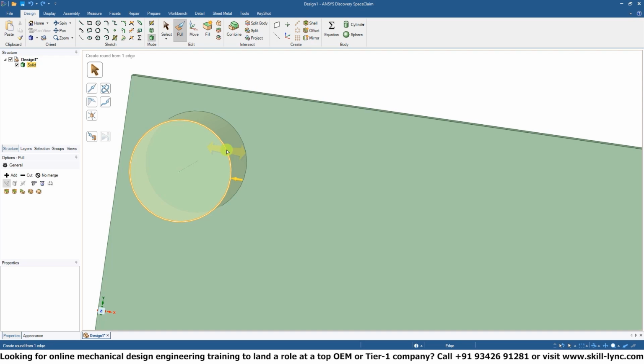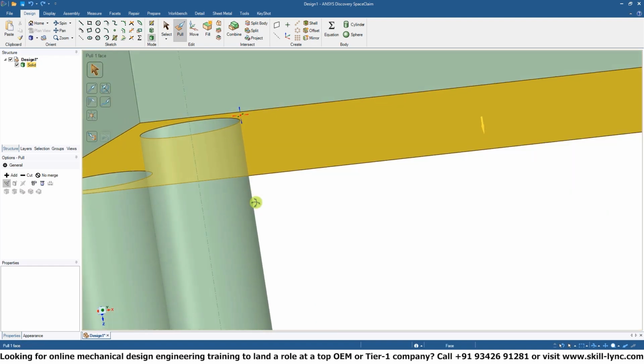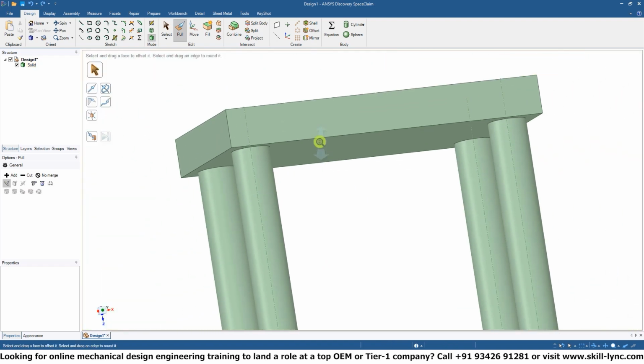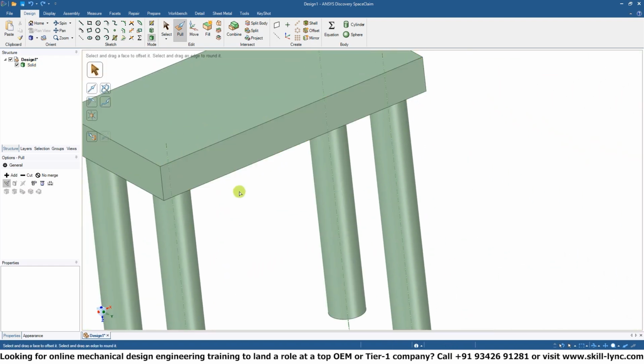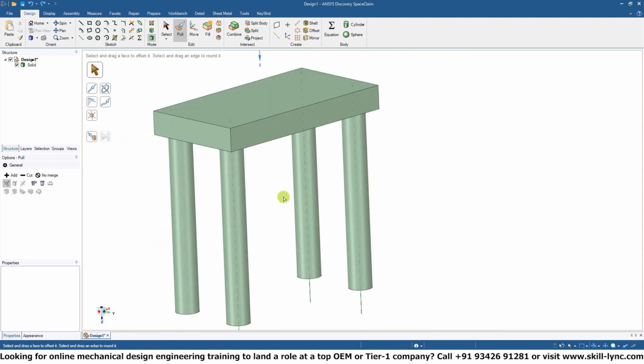What that does is it breaks up the geometry into many little triangular faces that make up the geometry. So this circle will be split up into line segments that form triangles on the face of the model. And this helps save a lot of memory, and it helps compress the files.